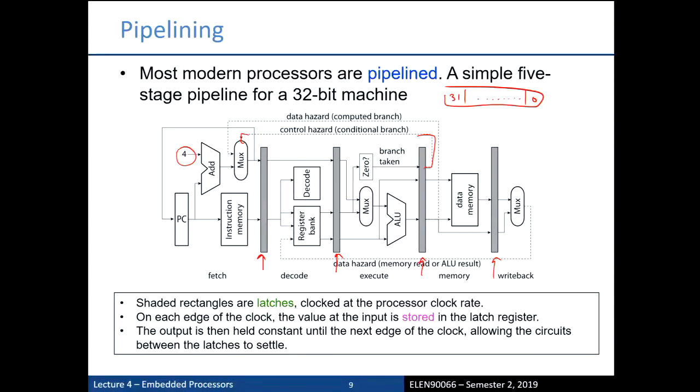There's also the mechanism in order to write the value, the output value, back into the register bank. And so this can cause problems. If there's feedback from previous operations coming back into some of the middle functional units, we've got problems.